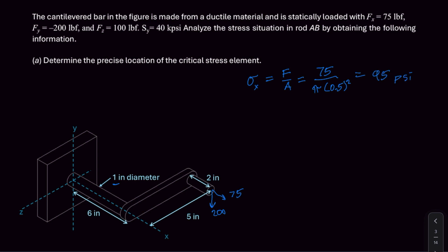So the axial stress is going to contribute very little compared to what we'll calculate for the bending stress in just a moment. So if we do calculate our bending stress now, that would be equal to our Mc over I. So that will be equal to the 1985 pound-inch moment.